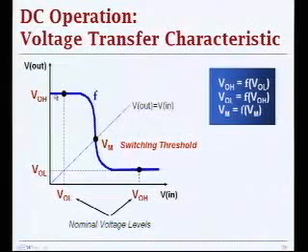This voltage transfer characteristic is described by the blue line with this function f. So when you work with nominal values and have an inverting gate, if you have VOL or logic 0 at the input, you will have VOH or logic 1 at the output, thus providing the inverting function. Similarly, when you have VOH at the input, VOL is the transfer function of VOH.